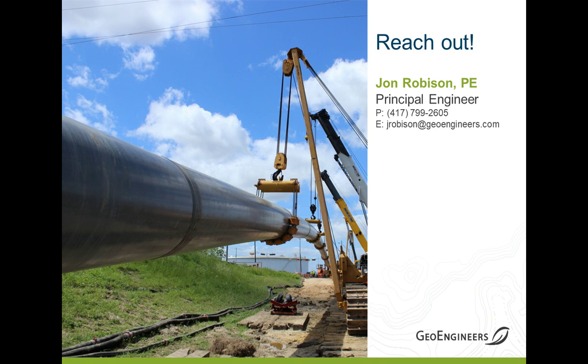So can you talk a little bit about the mud system that's required to accompany this method? Yeah, as we mentioned, there are two fluid systems. There's the bentonite lubrication fluid system that introduces bentonite lubrication fluid at the launch seal and behind the MTBM, and that's what fills the annulus space. And then there's the slurry feed and return system that runs in the 5-inch diameter hose lines that we showed a picture of, the umbilical lines.